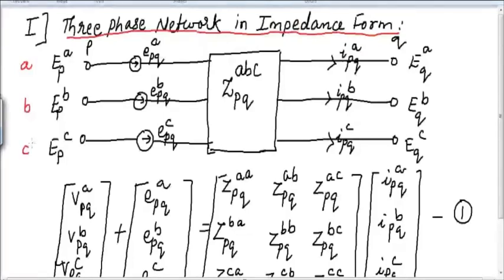Similarly, at the next point, you can see we have written P and Q. In the previous unit, that is unit number 2, we solved the numericals related to the Z-bus formation by algorithm technique. In that technique, we used to add element 1, which is a branch, then add element 2, which is a branch or link, whatever it is. And we used to check from where that element has started and where it has ended. That is, the start point used to be P and the end point used to be Q.